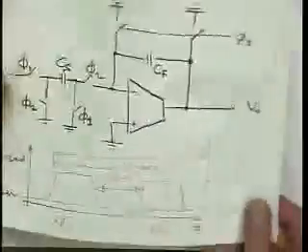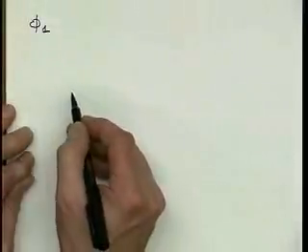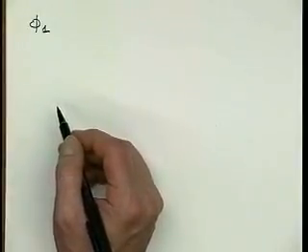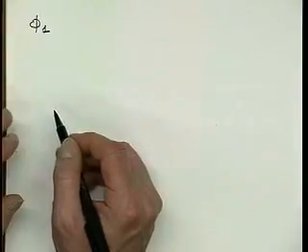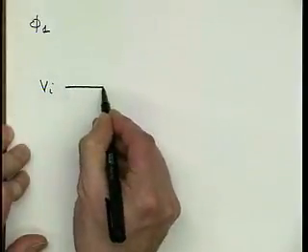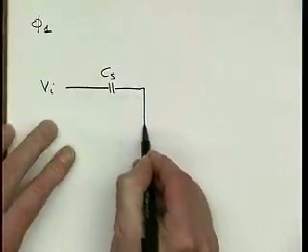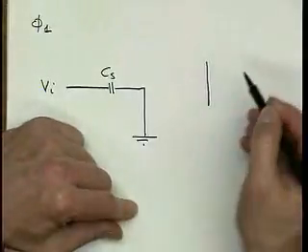let's now draw this circuit again during phase 1. Incidentally, this circuit is precisely the same one that is also in the notes. I just draw it here again. So during phase 1, all the switches labeled phi 1 are closed, and so they're short circuits. And all the switches labeled phi 2 are open and consequently can be totally ignored. So we have Vi that connects through a closed switch to CS, and CS on the other side also through a switch is connected to ground. The amplifier